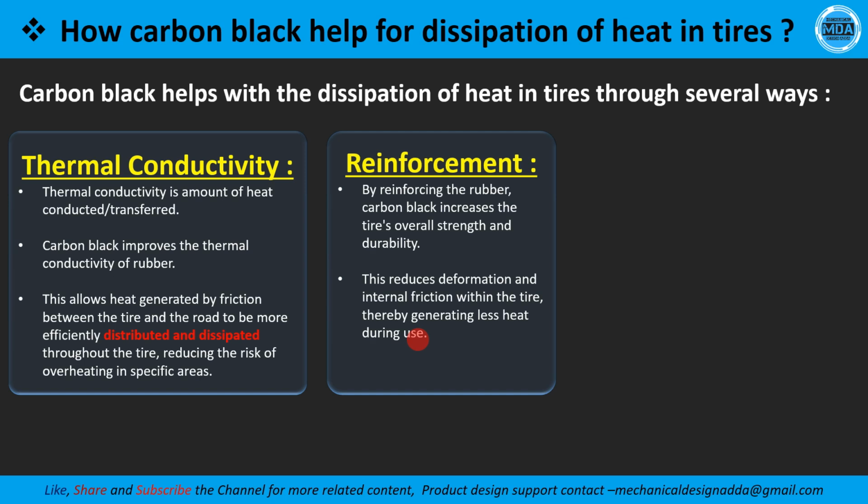Next is reinforcement, which means strengthening the tires. Carbon black strengthens the tire. By reinforcing the rubber, carbon black increases the tire's overall strength and durability. This reduces the deformation and the internal friction within the tire, therefore generating less heat during use.